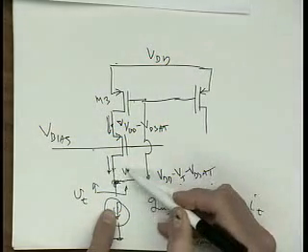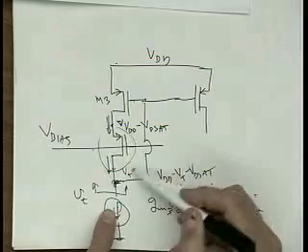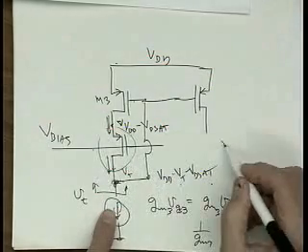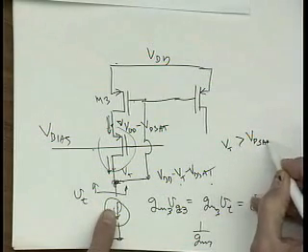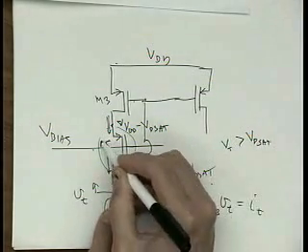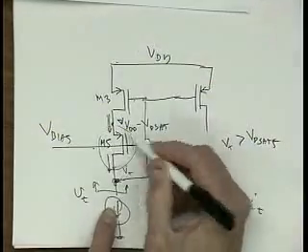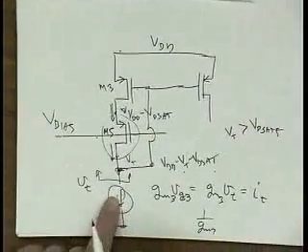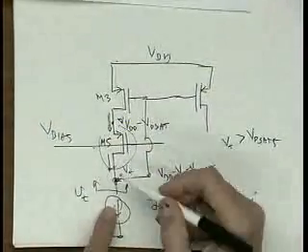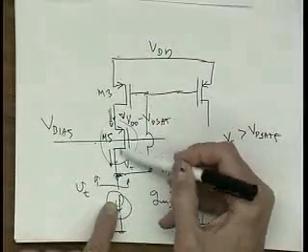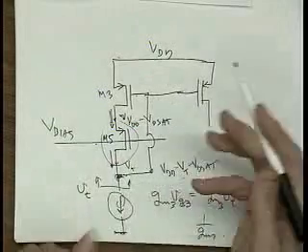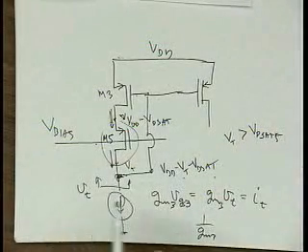So I have an extra VT here, and as long as the VT of this transistor is greater than the VDSAT of transistor 5, then this device is in saturation. Right? So you had to diode connect this somehow. If I tied it down here, then I'd have to figure out another way to set this voltage, and so this kind of does two things at once.